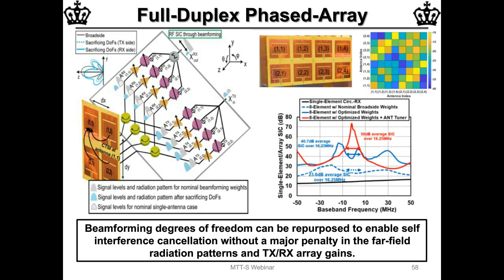And we've taken this circulator receiver subsequently quite far, actually. So we've built a phased array with multiple of these circulator receivers on the same chip, 4 of them actually, so a 4-element beam-forming circulator receiver array, where those baseband signals are now combined to give you phased array beam-forming.